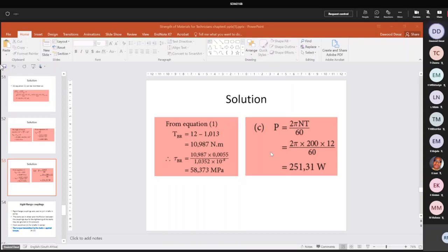We're not working in 3D, we're only working in 2D, but you can see it. You can see the 900 is turning anti-clockwise. The 600 Newton meter is turning clockwise. Use the same rule. Put your hand by B, put your hand by C, and work out what the net torque is on that section or that segment. They explain it to you here in your book also, if you read 6.4.